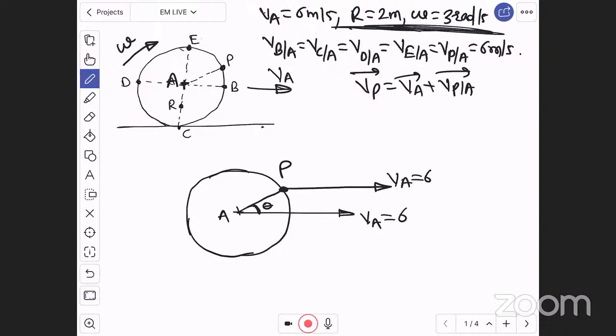And there is tangential velocity, and this wheel is rotating in clockwise direction with angular velocity omega. Therefore, can you imagine with respect to A, the point P will go slowly in downward direction. Therefore, there will be a tangential component at P which will go downward. Tangential component is perpendicular to the radius, that is, perpendicular to RAP. So draw perpendicular to RAP like this. There will be a velocity of P with respect to A, which is perpendicular to RAP.